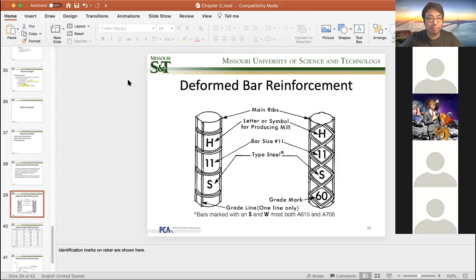So right now, in the market, you can see that most of the ribs, like the rib right here, look like this, okay, especially this threaded one. We have some of the helical ones, but nowadays more like this, okay? The spacing between the ribs over the rib height is normally between 7 and 10, and that's why we have a standard shape for the ribs, okay?